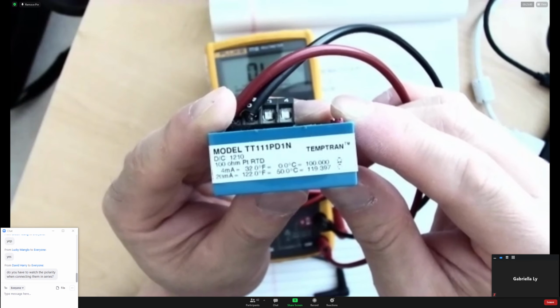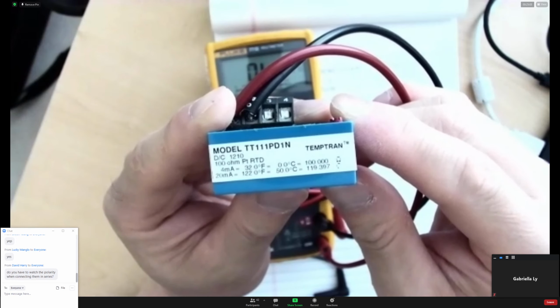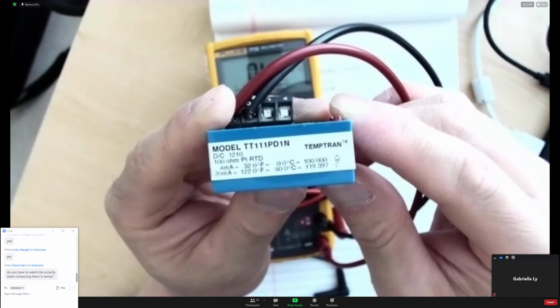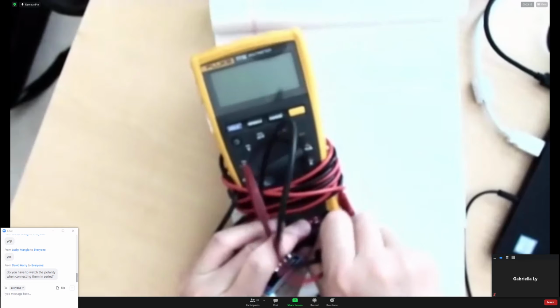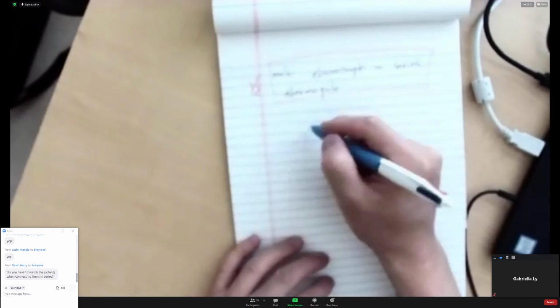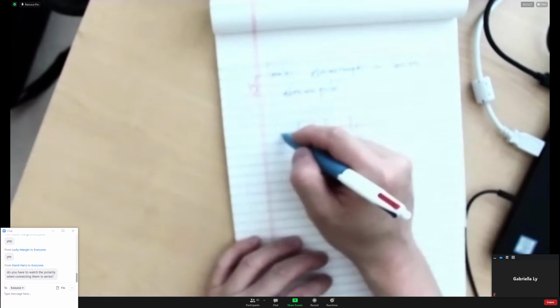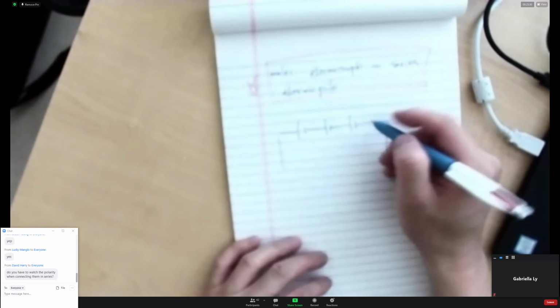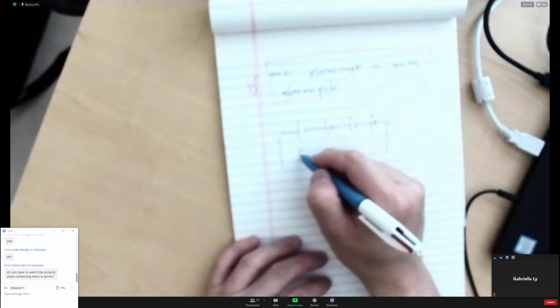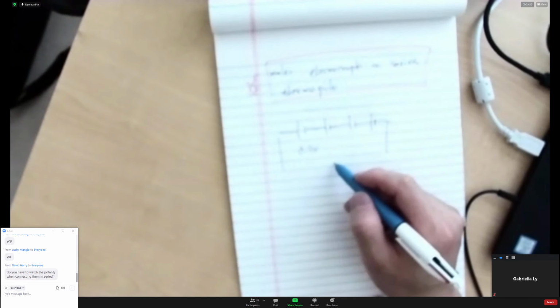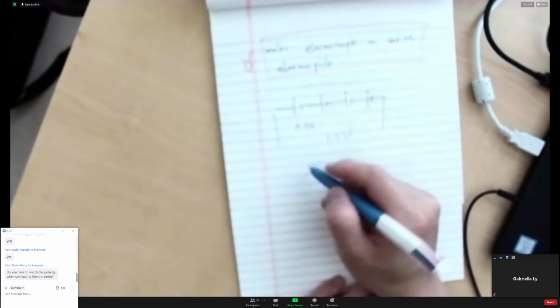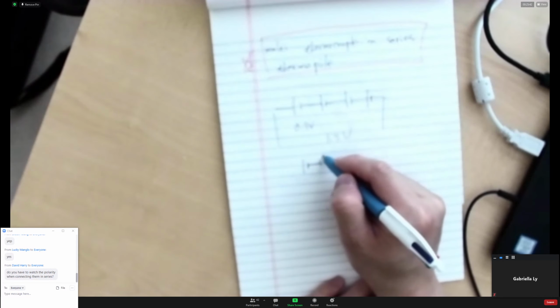When you're talking about the thermocouple, when you wire them, yes, you have to watch the polarity. If each of them, let's say put a 4 down here, it's 0.3 volts. We connect this one, we can get 1.2 volts. But if we don't watch the polarity,